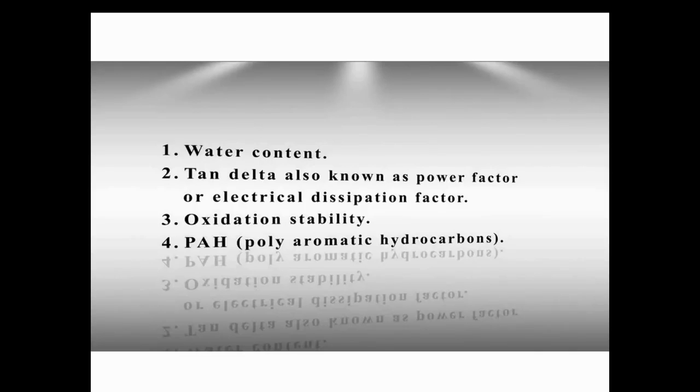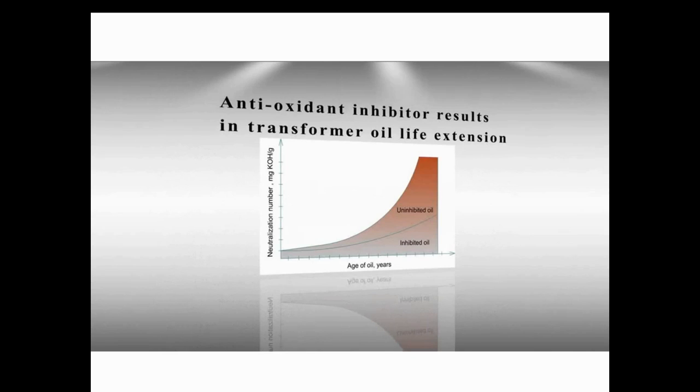To assure good quality of transformer oil, we should pay the most attention to tan delta, which is the crucial criterion for evaluation, especially when it comes to high voltage transformers over 400 kVA.